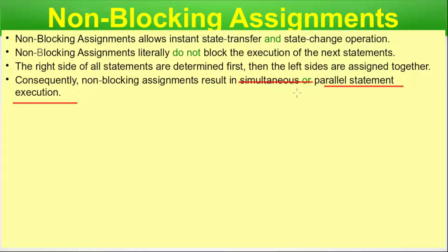So here it is much more realistic, because in real time, when you have real time data going on, many assignments or state changes will happen concurrently. So the concurrent behavior has to be addressed inside Verilog, and that is addressed by the non-blocking statement.